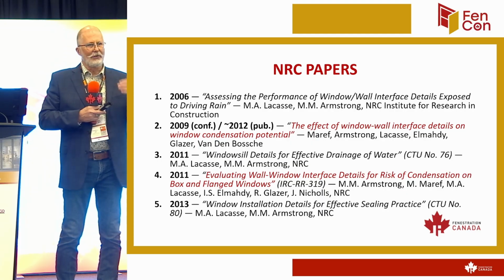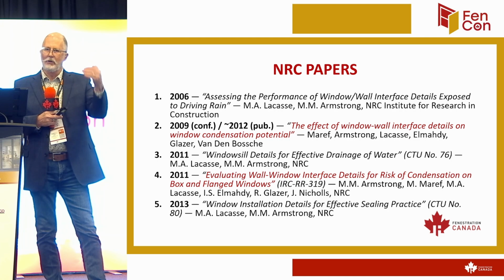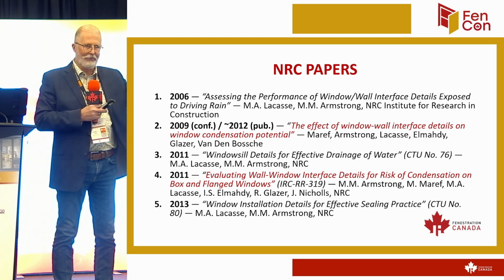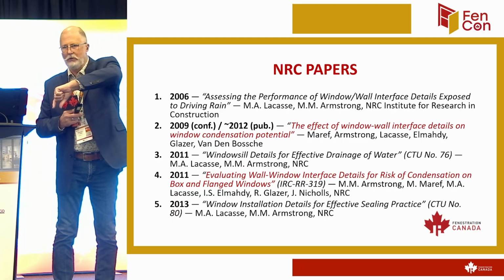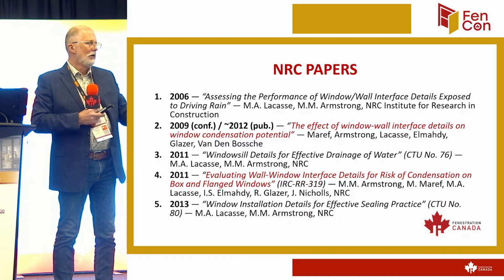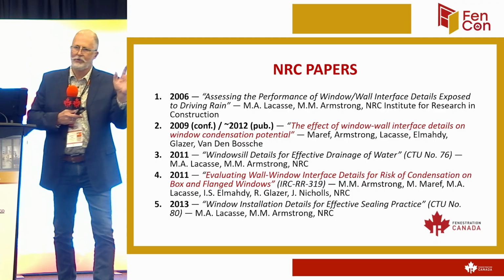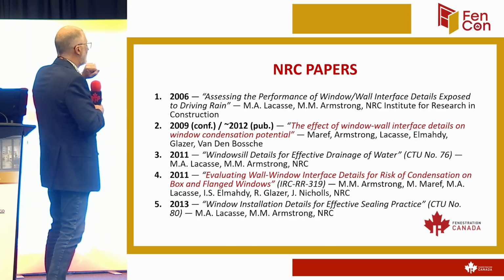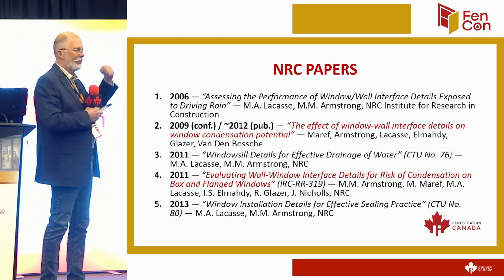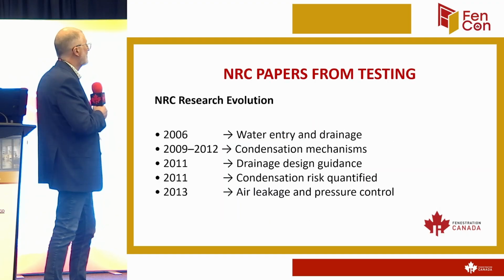So the temperature difference on the inside face wasn't affected by not insulating the sill, as long as you had a good air barrier on the interior face of the frame, and on the exterior you sealed the sides, the head, and the other side. The type of insulation was almost irrelevant to the interior temperature. So they continued to take the data and the information and produce additional documentation because they'd tested so many things and had so much information to write about.